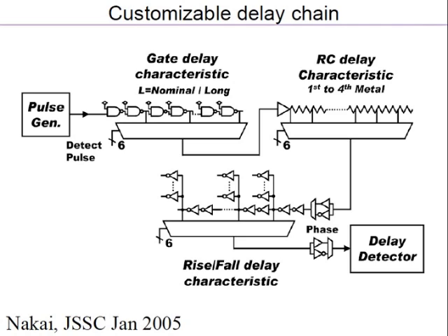Correct. So you can have what is called a Schmoo test, where you run the test just as I described. You run it and you see at what voltage it fails for that frequency, or for that voltage at what frequency it fails. If you are testing for multiple different voltage points, you have to set it up, and then you can get that Schmoo plot.